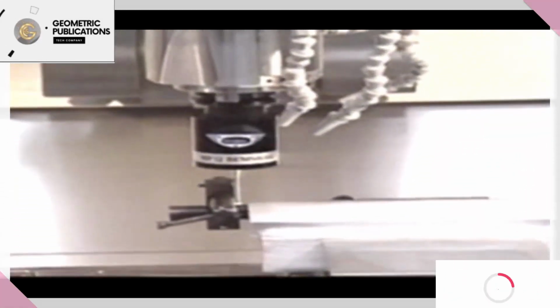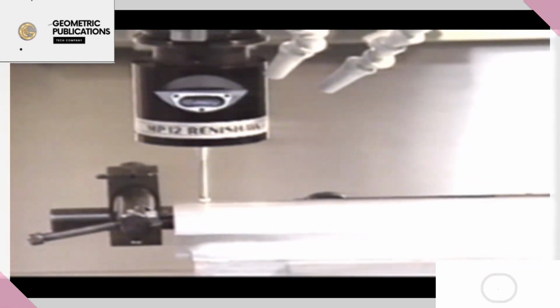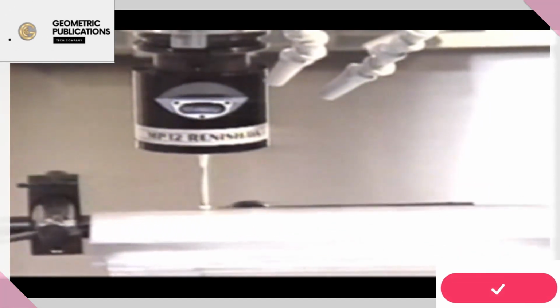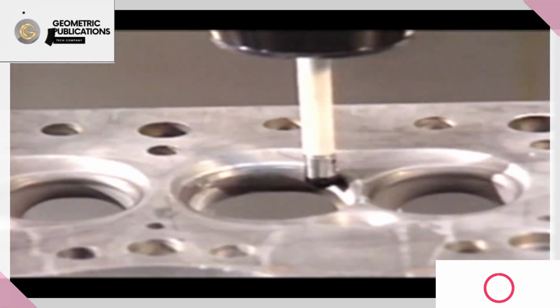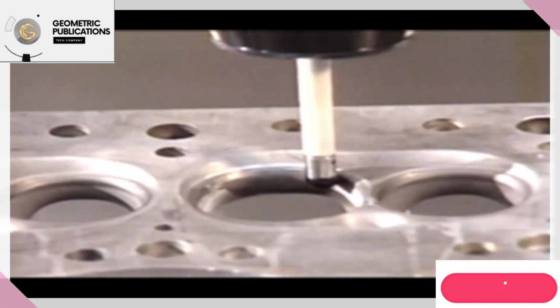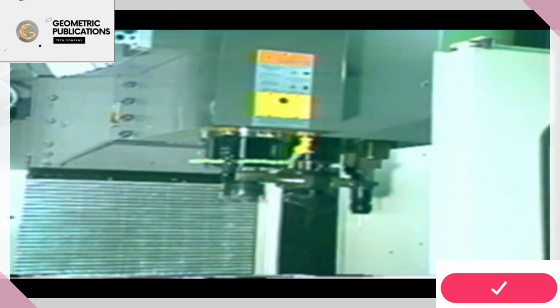Of the many accessories that may be used on machining centers, two are significant. One is the touch trigger probe. Together with appropriate software, the probe can perform measurements on workpieces before they are removed from the machine to determine if certain features are dimensionally correct. Probes are stored in the tool magazine.